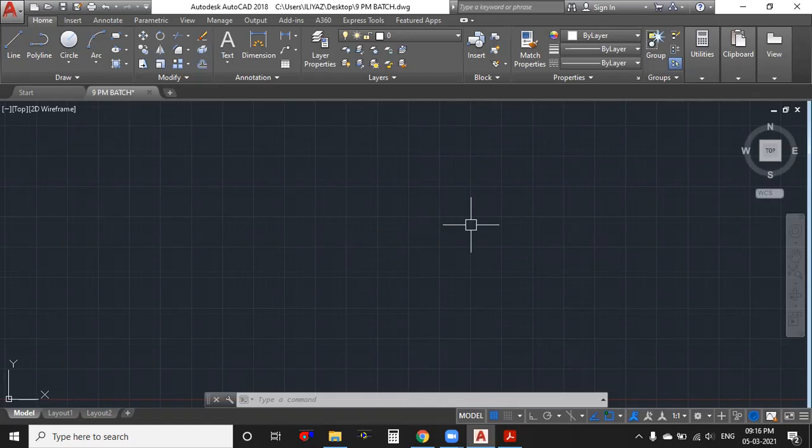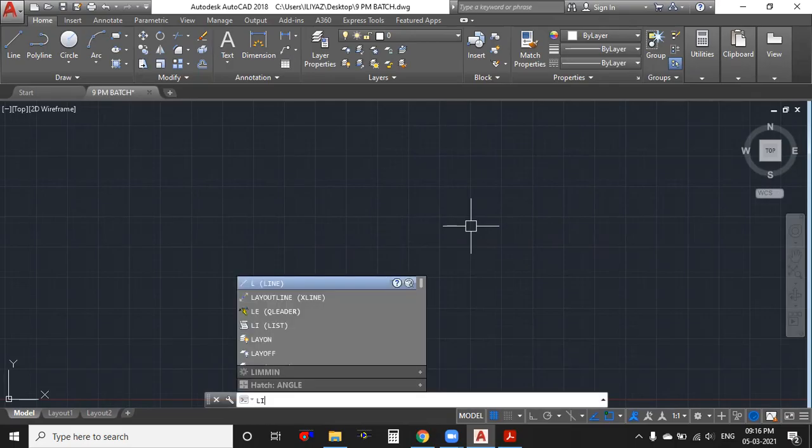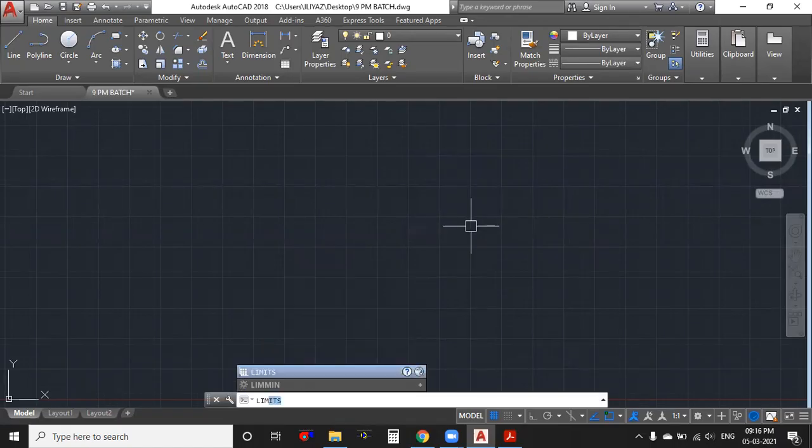If you are working on a project file, we don't know where that file gets saved, and we can't search for it. For that, we create a certain boundary for our space. However much boundary we require, that much I am going to create. To create the boundary limits, just type LIM. If I type LIM, it takes the default command Limits. You can see it downwards, limits, enter.